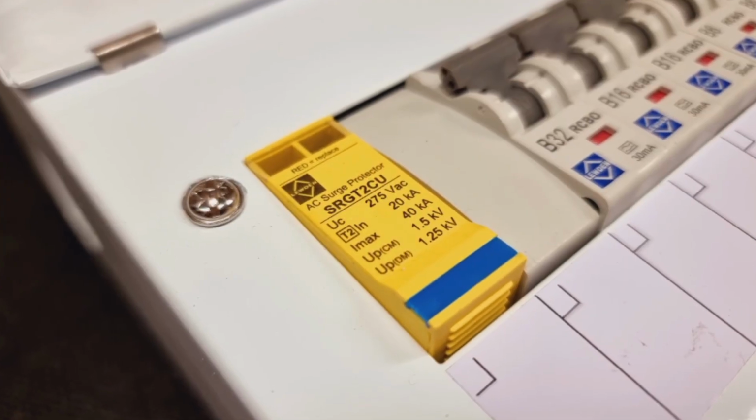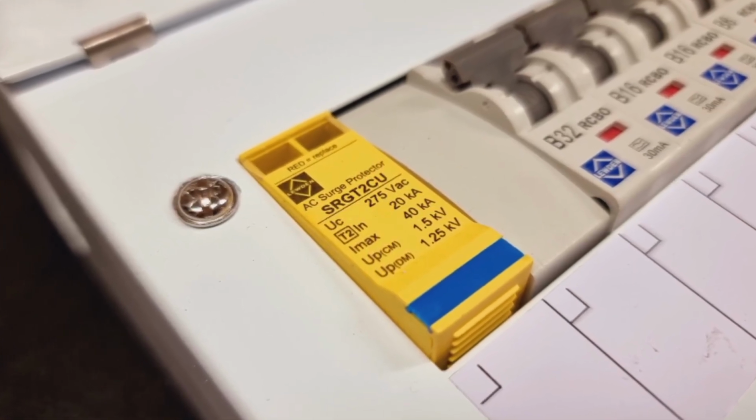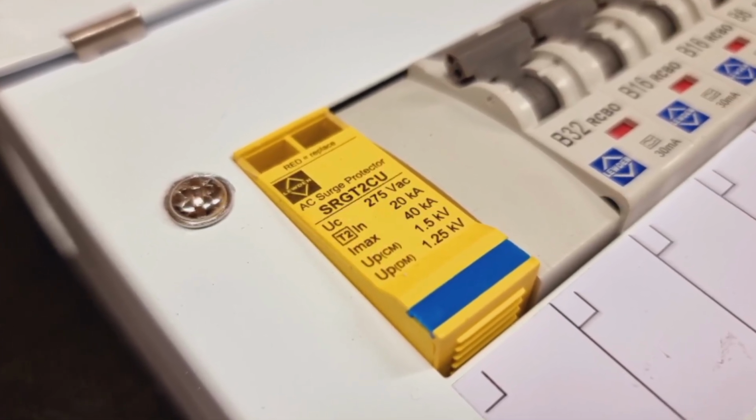Well, a surge protection device, or SPD, is designed to deal with intense but incredibly brief spikes in the supply voltage. These can be caused by many things. Depending on many different factors, these spikes can happen relatively often or hardly ever. But a surge protection device is designed to kind of cushion the blow of these spikes while keeping the electrical system active and operating safely. You'll probably have noticed on an SPD there's no reset button because it doesn't trip. The device just works away until it eventually needs replacing.